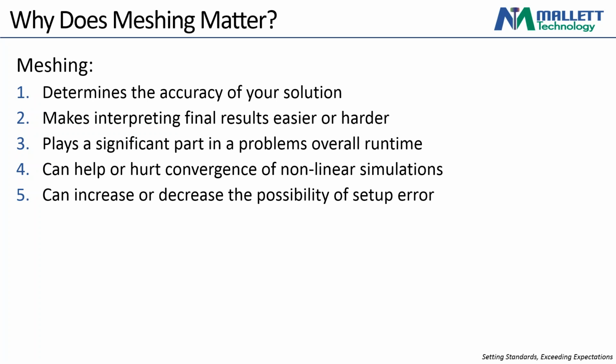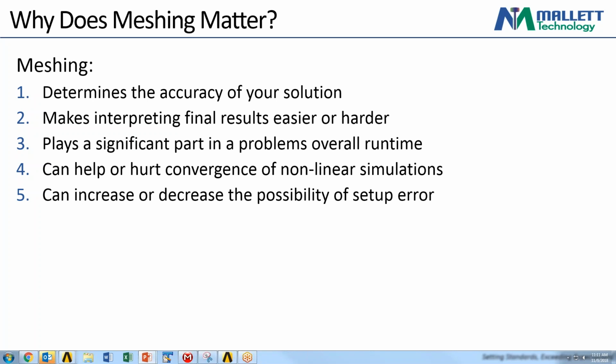Third, meshing plays a huge role in the overall runtime of your problem, right? More elements equals greater runtime. So understanding how to mesh efficiently is a big factor in optimizing your runtime. For some jobs, let's say static structural jobs, where it's really just one run, one iteration of solving the stiffness matrix, oftentimes you can just throw a ton of elements at it and hit solve, right, because it solves relatively quickly. But for jobs where you're going through a number of iterations, let's say a transient shock analysis or a modal analysis where you have to pull out a number of modes, those are cases where you really truly want to optimize your element sizing or the number of elements, because otherwise you're going to dramatically increase your runtime, you're going to dramatically increase your solution size, and with that comes a whole slew of additional challenges.